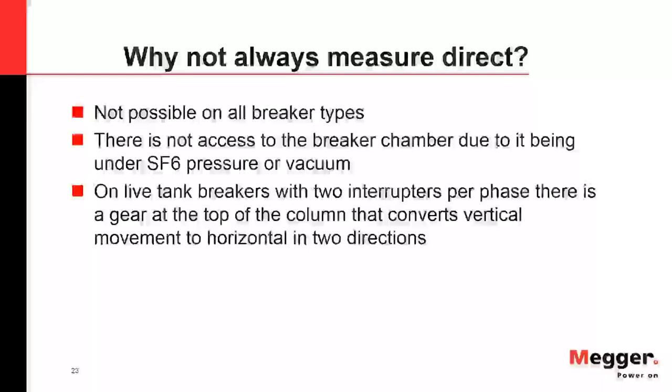So technically you can do this live. Some manufacturers make online monitoring systems, but you have to have your transducer always hooked up. And depending on the type of circuit breaker, if that transducer is sitting on top of the circuit breaker or up in the air where the parts are live, you really can't have a transducer up there because it's going to be live, and you can't isolate the cables and all that. So it depends on the type of circuit breaker, but I have seen people hook up a rotary transducer somewhere where it's safe, below the conducting or high voltage parts, and run a test while it's live. But I would say 99.9% of the time, this is an offline test. So you don't really want to be doing that when the circuit breaker is live.